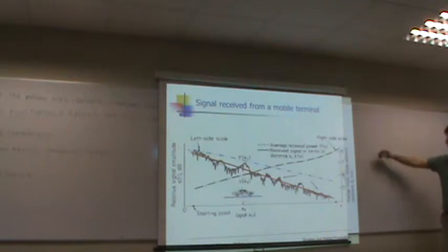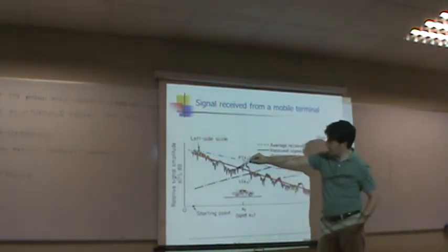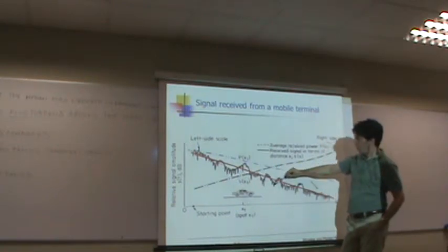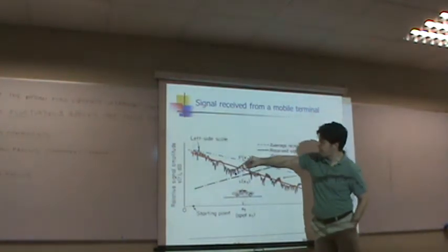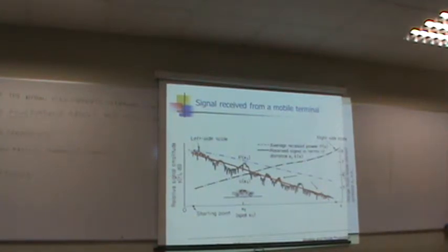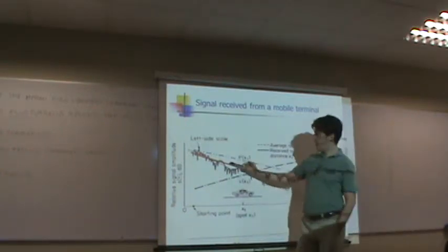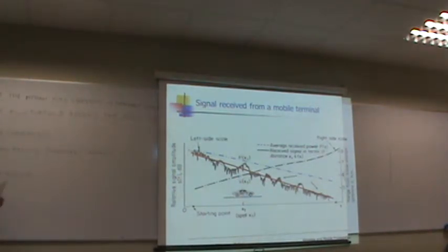So when these kind of obstacles that are quite large, buildings, etc., enter or exit your scenario because you are moving, they are fixed, but you are moving, they cause this very slow fluctuation. Here you have more signal, here a little bit less. On average, what you get is the red line.